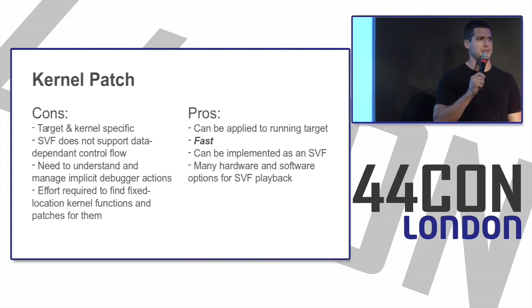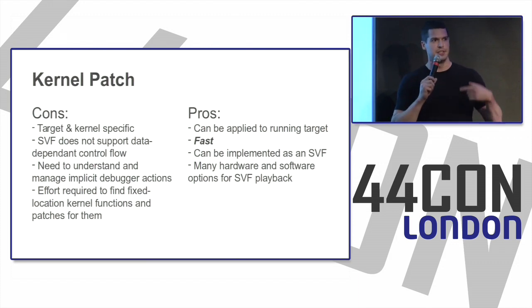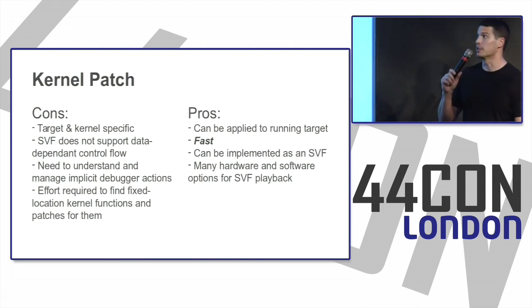This is not kind of fast. This is not pretend fast. This just takes a couple milliseconds, and that's just the time it physically takes to shift all the several hundred bits through the JTAG adapter at a couple megahertz, and that's really about it. So there's very little overhead in the delivery for this one.